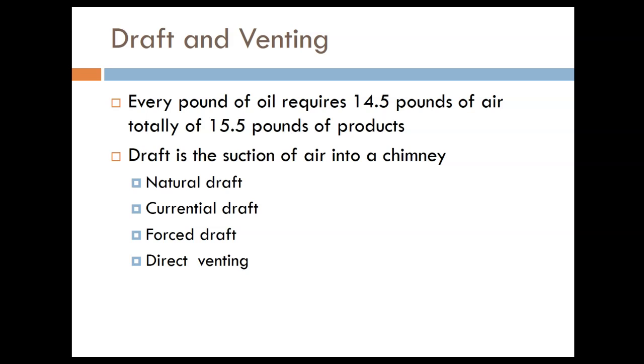However, there is an advantage to pulling air from the space, because the air inside the basement or wherever you install the boiler is warmer than the air outside, and that will improve the efficiency of burning the oil or gas. So there are advantages and disadvantages, but when in doubt and if you have an option, you use the sealed one, so at least you guarantee that the boiler will get all the air it needs from the outside.